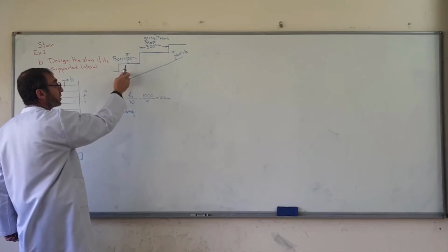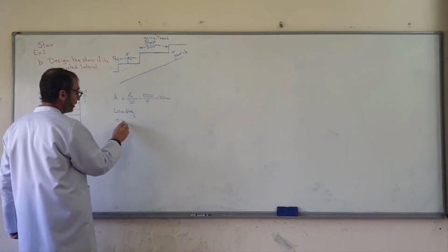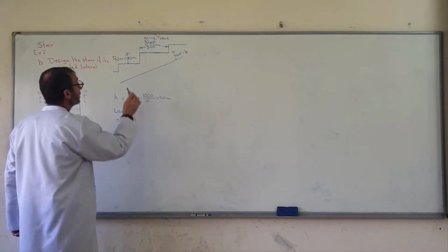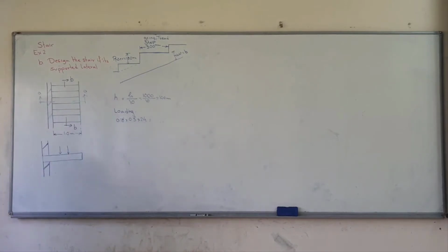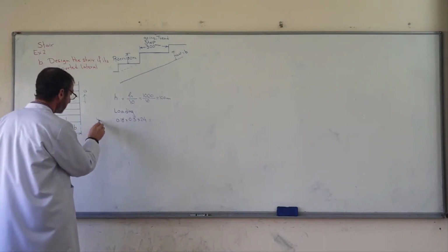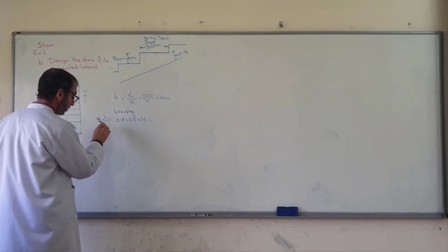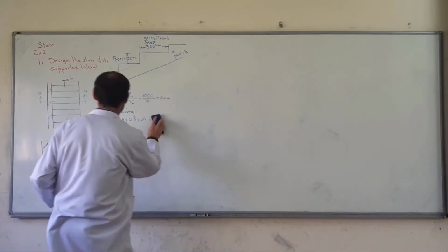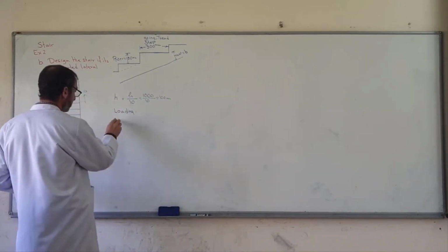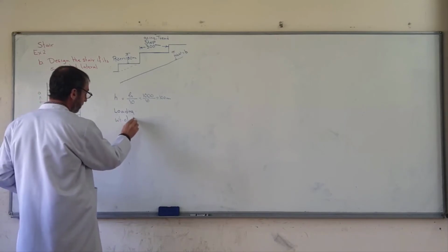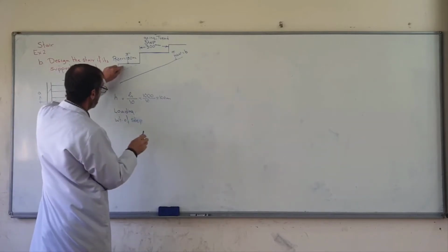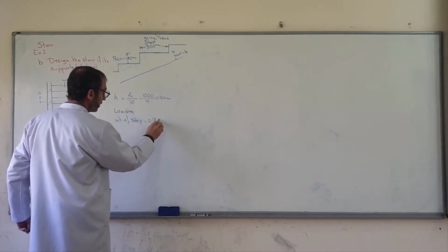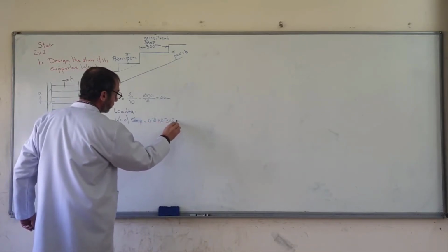Self weight of a step is 0.18 times 0.3, with 300 millimeters as the tread, times 24.